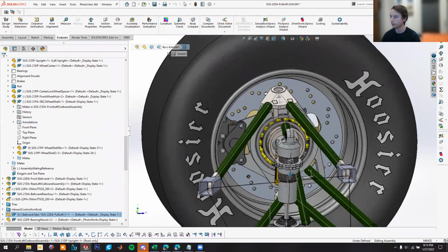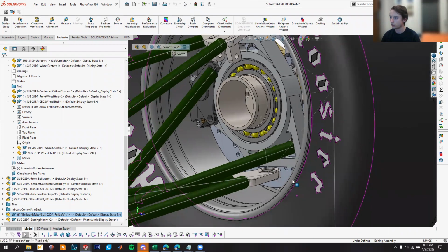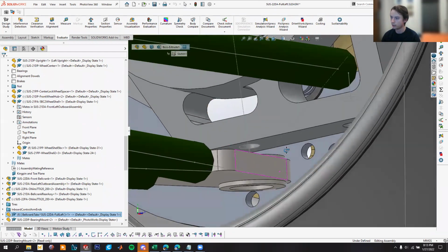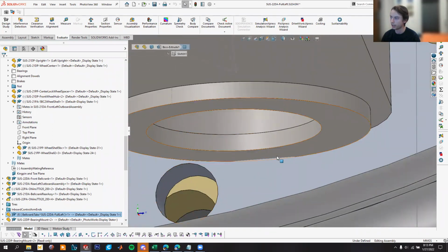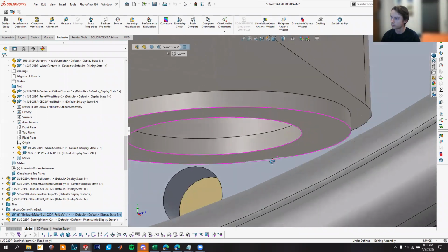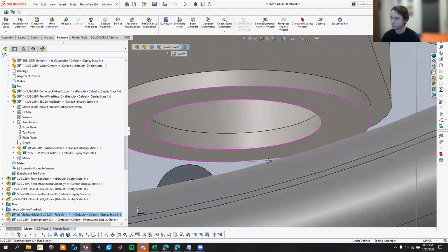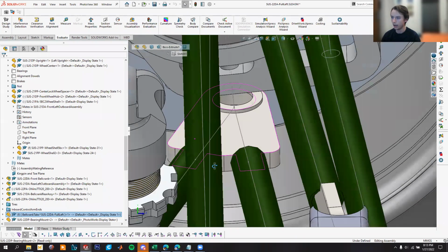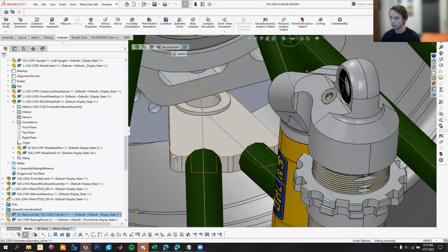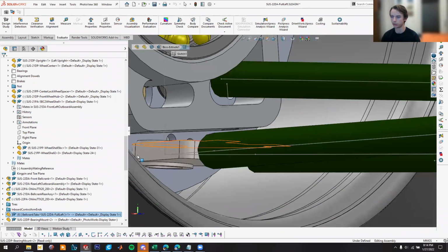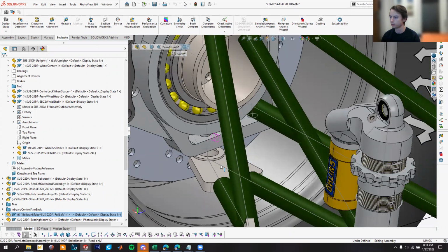They could probably all go a little bit smaller if they can, but it's to adjust for this interference right here. And then this overhang material can probably come in just to reduce weight of the part, but that's not as critical as just slightly reducing that diameter if that's difficult.